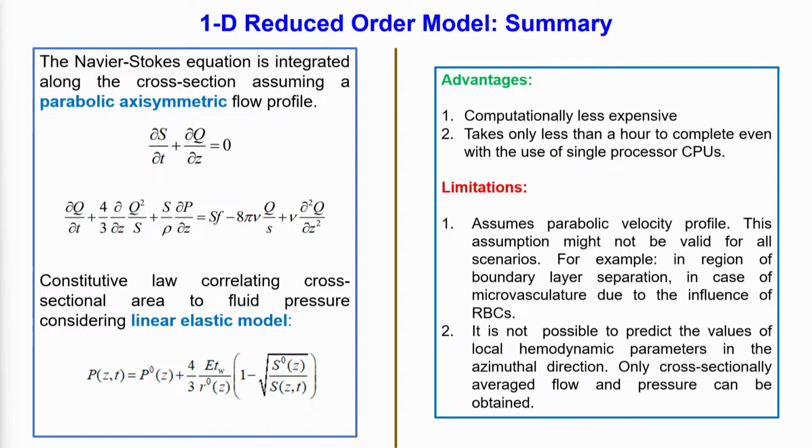exactly the same as that one, and the square root of S appears because we are talking about radius, and radius is proportional to the square root of the cross sectional area. A perfect circle is pi r square, right. So that is how the square root of S comes. Once you do that, this is the constitutive behavior, that means how pressure varies with local area, local thickness of the blood vessel and the modulus of elasticity. So with this you can solve these coupled equations.